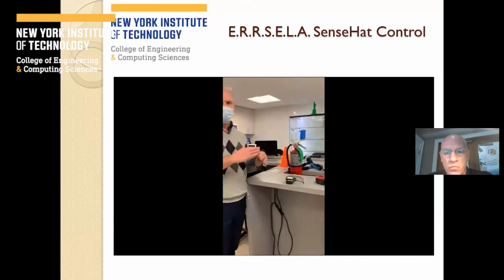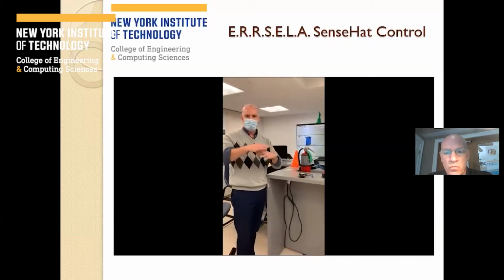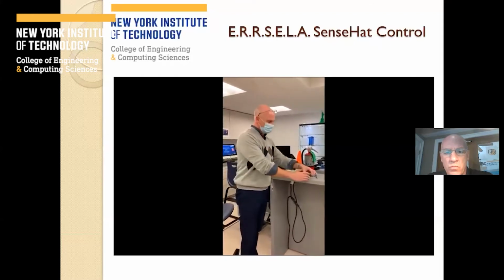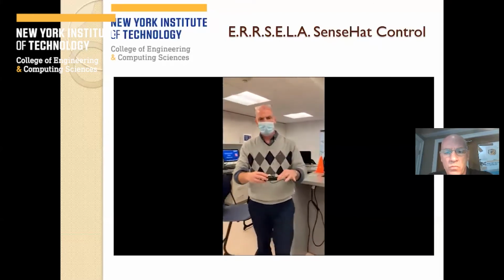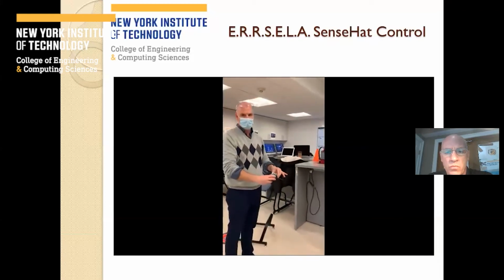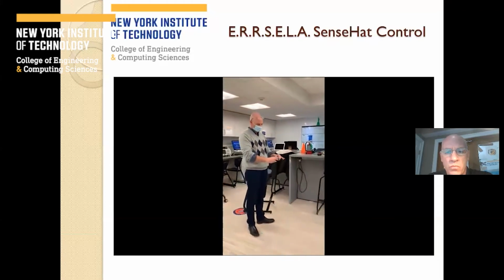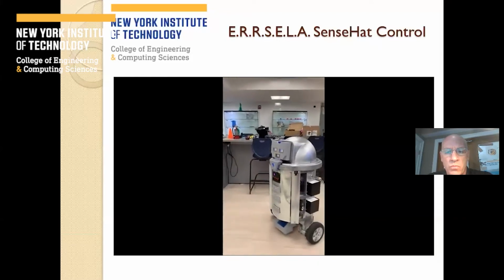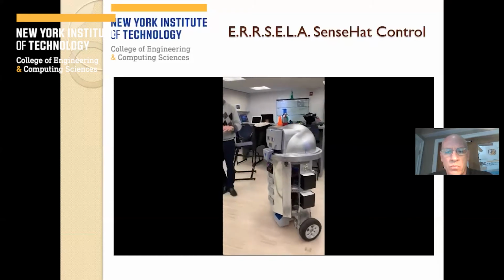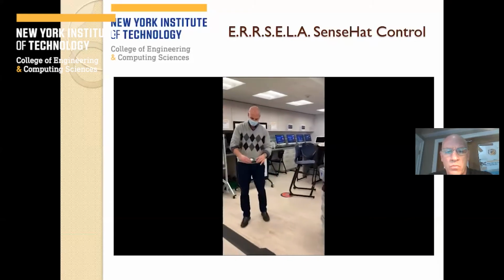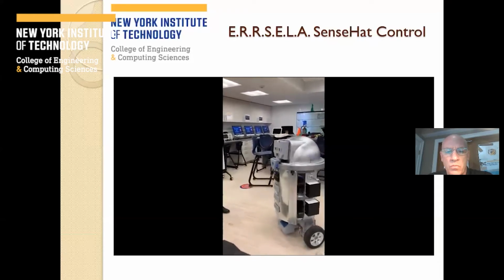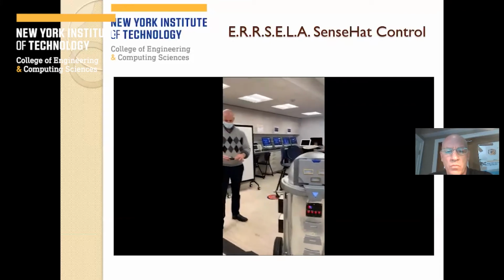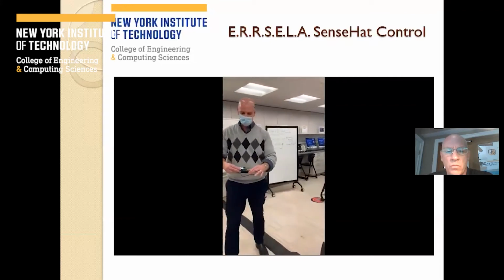So as this device changes, using the accelerometer, changes forward momentum, reverse, or left or right, it's going to sense that. And we programmed it that when it senses it, it sends through the API, through the Ursula API, the proper coding. So if we turn this way, we see forward, and the robot moves forward. Forward. Okay. If we turn left, we see an L through the coding, and the robot turns left. Left. Okay, and then if we move backwards, it's just going to send a stop signal.